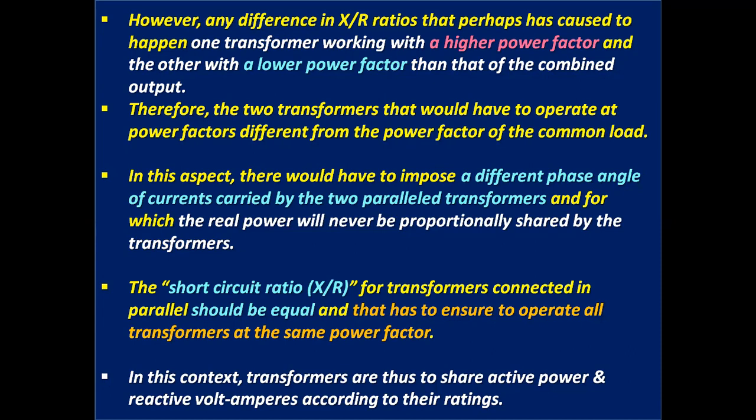The short circuit ratio X by R for transformers connected in parallel should be equal, and that ensures all transformers operate at the same working power factor. In this context, transformers thus share active power and reactive volt amperes according to their ratings.